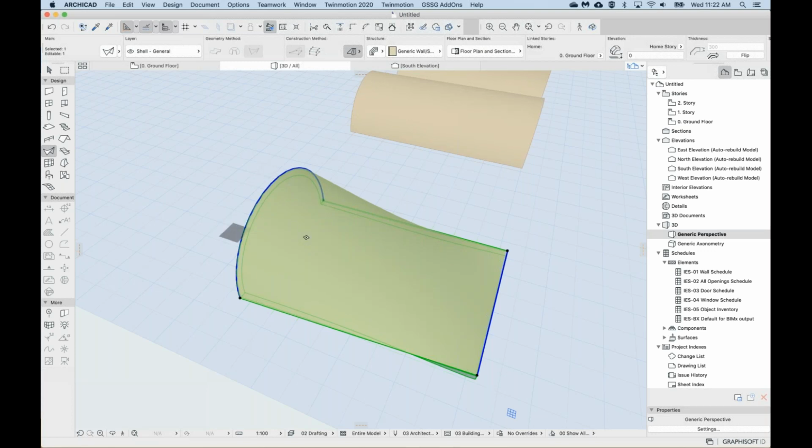I tend to recommend to try to get the same number of points on both profiles. So if we have, say, 3 or 4 points on one profile, try to get 3 or 4 points, so the same number on both profiles, because then the connection between the two will be simpler, because it will basically connect the dots between the two profiles.